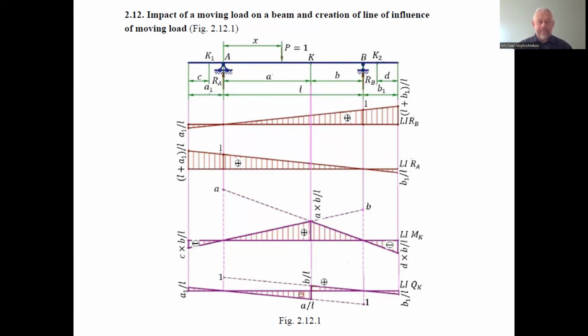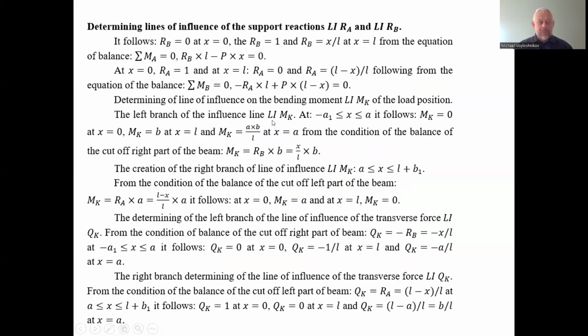For example, considering the balance equation of the rotation of the unit force and reactions around the point A, the total of the moments rotating the beam around the point A is equal to zero.